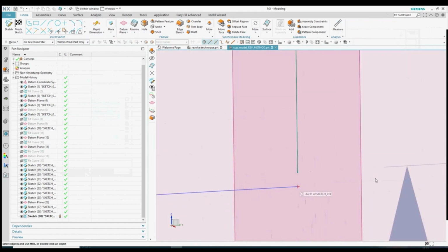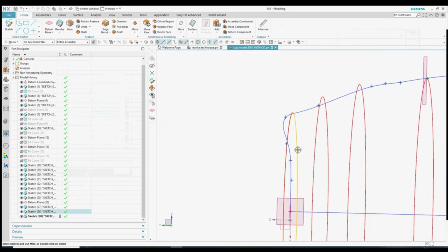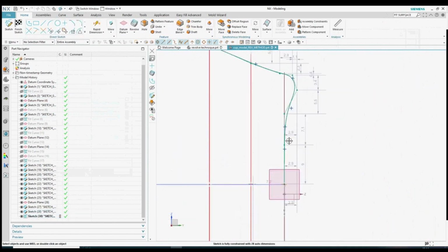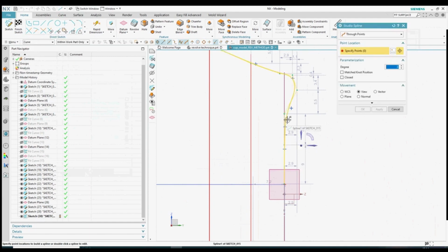And these are the differences between the Bezier curves and the B-splines. We'll go through that in detail when we are talking about the theory. But for now, all you have to remember is to use the through poles command for a better local control.